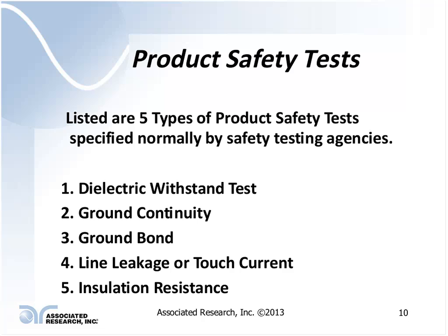So this is to measure a potential shock hazard that could exist within the product if you introduce some fault conditions into the product, or possibly some potential errors in the input where the input potential may be reversed as far as the polarity, where your line and neutral conductors might be reversed, or you have an open neutral or open ground condition. What kind of potential hazards could exist to the individual if these fault conditions were introduced into the product itself?